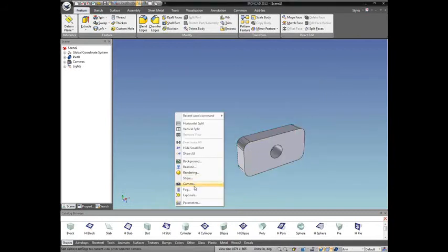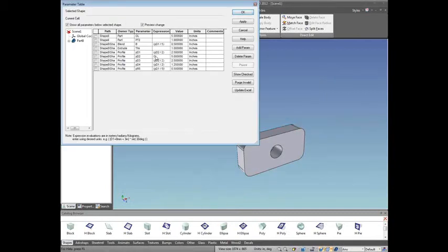Well, I can reference it here in the parameter table. See, and this is where I can see. So what I did is I created a parameter that I then put into the size box table that we saw before in the IntelliShape properties. So now if I change the parameter here, the thickness will change. But all these other parameters are created by dimensions, profile dimensions, so they're just the length and width values, basically, not the height.